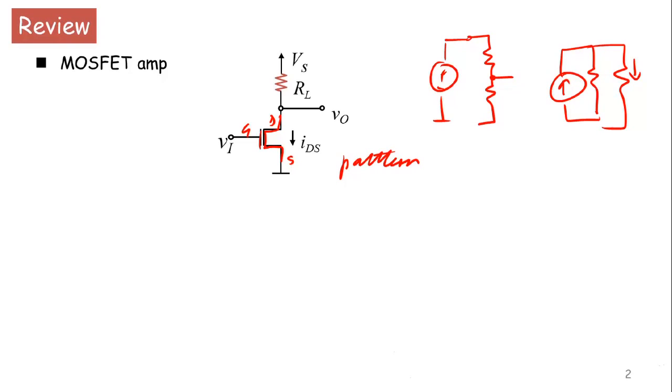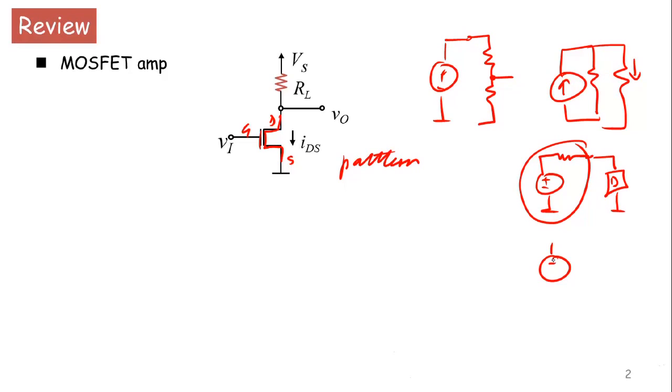Another really key pattern that we saw was the Thevenin pattern, where I replaced a bunch of circuitry with this pattern, and then I connected some device D, the interesting device, to my Thevenin pattern. So a voltage source in series with a resistor, which in turn is in series with a device of interest, is another pattern. A complementary pattern, which is the dual of the pattern above, is a current source pattern, a Norton pattern, with a current source and a resistor, and we connected that to some device D of interest. This is another very common pattern.